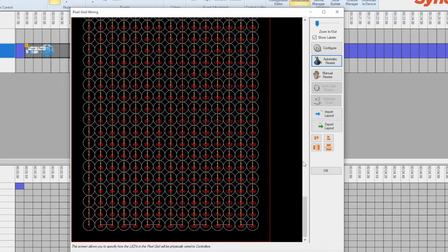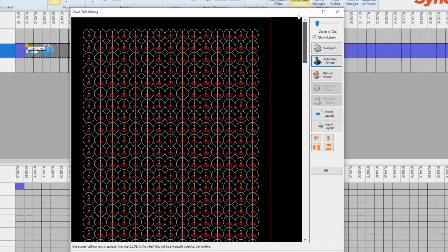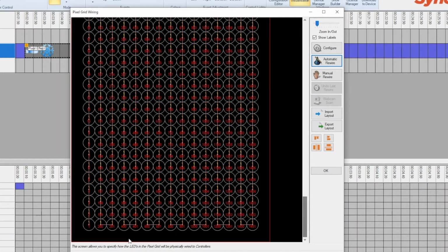And then that goes up the tree. So the first strand goes up. And then at the top of the tree, you wire the end of your first set of pixels into your second set. And then it goes down the next. So you have to think of the tree being flattened into a grid. That's all a pixel grid, pixel megatree is really. It's a stretched out grid that's stretched out at the bottom.